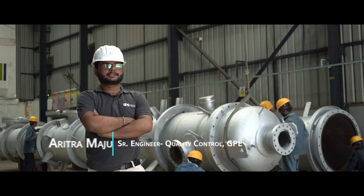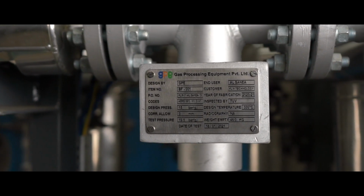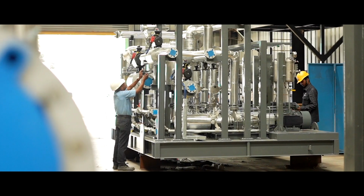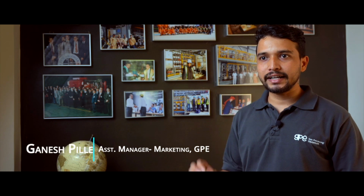Construction and design is as per ASME Section 8 Division 1 and measurement and tolerances as per API refinery standard and specification. During fabrication, we carry out the in-process inspection and the same will be verified by TUV, the third-party agency. We understand that the key to success is standardization and modularization.